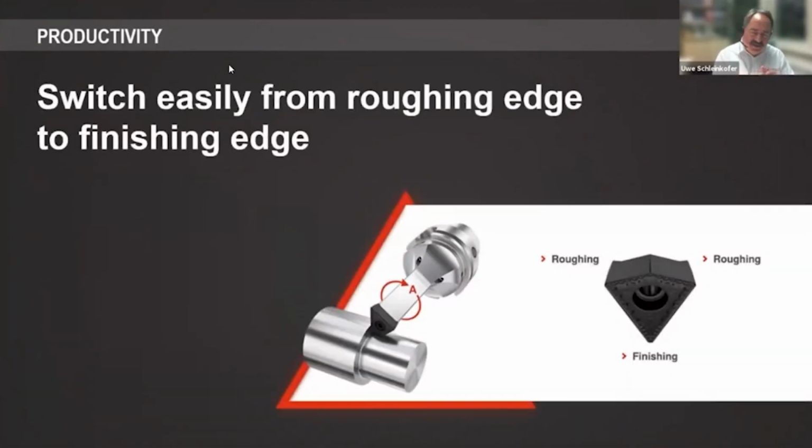So another thing is, I mentioned the tool holder in the machine, the tool revolver. Here you have maybe the smallest tool change system in the world, because here we have an insert, and this is available, where we have two cutting edges with a roughing chip geometry and a roughing geometry at all. And we have one tip here with a finishing application incorporated in one insert.